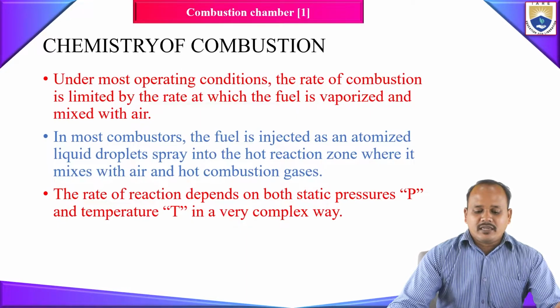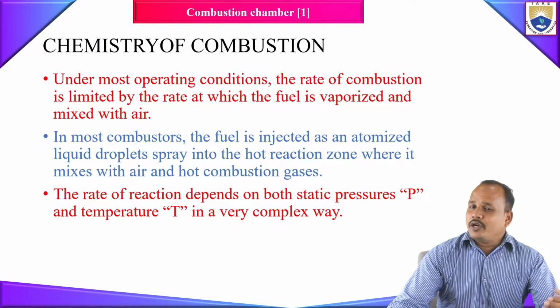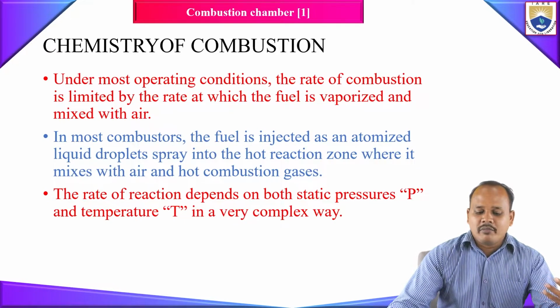As we have stated, what is the function of your fuel injector? It is to spray the fuel in fine droplet form. Why do we have to spray the fuel in fine droplet form? Because the incoming air from your compressor has a certain amount of temperature. We are increasing the pressure across your compressor, and due to that, the temperature also increases. So when the fuel is injected into this hot gas coming out of your compressor, due to this temperature your fuel will evaporate. Basically, from liquid it becomes gas. When it becomes gas, it will easily dissolve and mix with your incoming air.